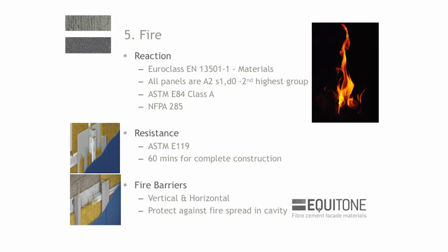Resistance is normally something that stops the fire getting from this side of the wall to that side of the wall. And that includes the complete structure, by the way. So it's the cladding, the cavity, the insulation, the fixing systems, your sheeting board, your framing system, and your plasterboard on the inside. So for that one, it's a systems test.